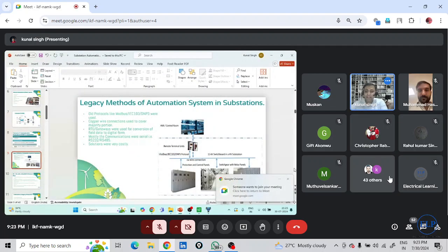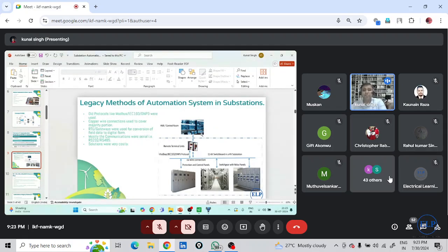So first of all, we wired it through copper wire to the IO card of the RTU. Then in the RTU, we converted it to some digital form in protocol X. Then based on the address, we did the column matching in this RTU software itself to protocol Y. And this device understands protocol Y, but this RTU can understand both X and Y. So it got X and converted it to Y. If there is another device which understands X, it will reflect the same X address to that device.